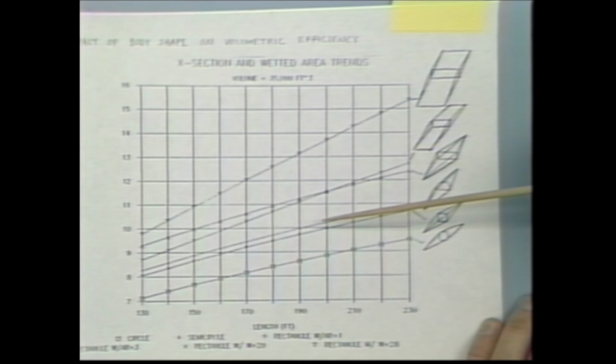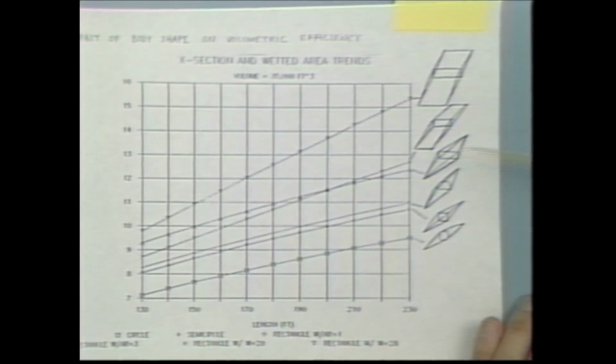The more wetted area, the less volumetric efficiency. More wetted area means more weight, more skin friction drag, etc. Down at the bottom, the highest volumetric efficiency is in round shapes. Think cones. Round shapes tend to be more volumetrically efficient. And as you go to square shapes, it does become less volumetrically efficient.